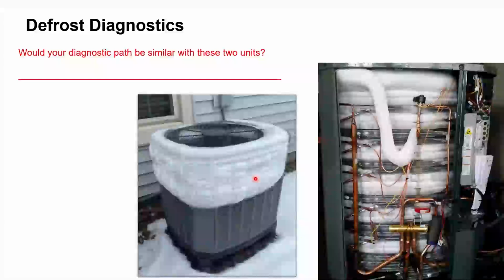Indoor airflow is another critical step. Then our refrigerant charge. Let's clear out this coil completely. To check refrigerant, we're going to have a clear and clean coil. Then we can fire up the system and let it run for a bit. We're going to gauge up on our discharge and our true suction here, and we're going to reference our charts in the service facts that are going to get us kind of close. Remember, you've got to verify airflow before we can verify charge, because if airflow is not right, we'll never get charge correct.